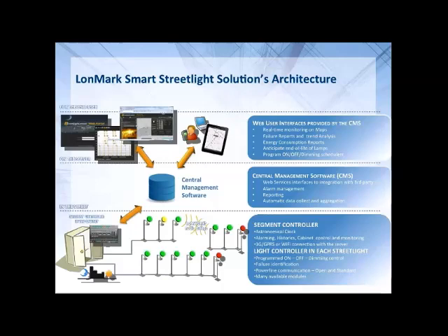It's a piece of electronics inside the pole, inside the luminaire, or on top of the luminaire, and its goal is to control the LED driver or the electronic ballast or even the conventional magnetic ballast, to measure the consumption, the power, the voltage, the current, the energy, the number of lamp burning hours, but also to identify lamp failures and dim the light level depending on schedules.